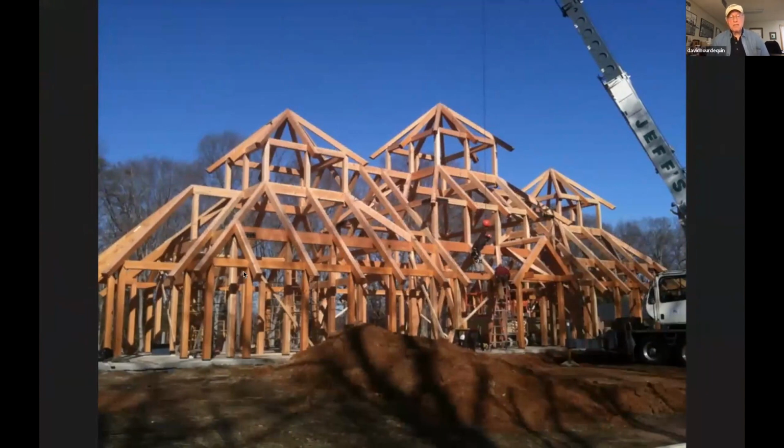So this structure had 3 square areas that were co-joined or had common walls in an elevated stack, and the intriguing thing about it was that the top plate up here is a tension ring. You can see the rafters all going down here. They're connected at the plates going around it, and they're trying to push that thing out. If you imagine a load down at the peak, it just wants to spread everything apart there. So up at these corners, you have to put straps around the corners or knife plates inside the timber or something to take the tension.